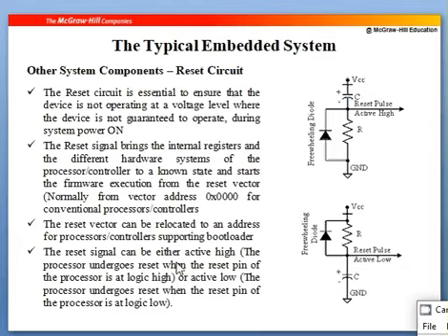So what happens when you press a reset button? We know in ARM Cortex you have a vector table for exceptions and interrupts defined, and the vector address 04 is for the reset handler. So in that address you have the reset handler subroutine starting address.